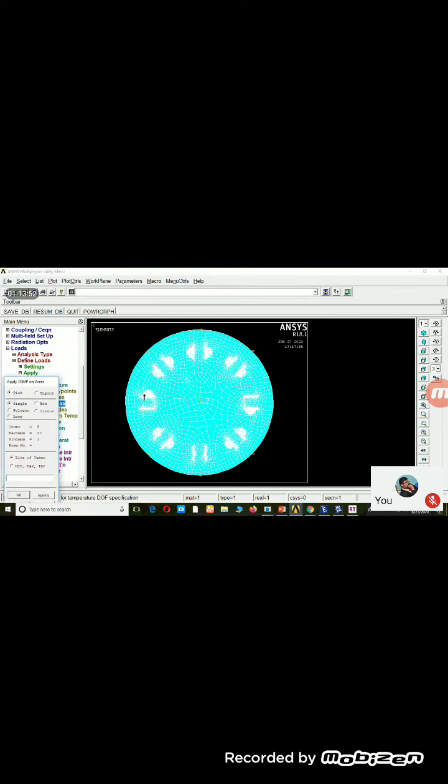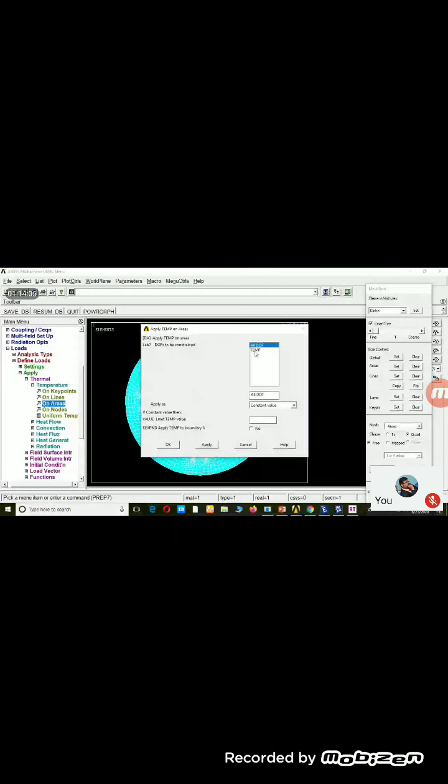Select the area temperature, that is the temperature found in the coil. Either we can go for the temperature as the heat source, or we can go for heat generation as the heat source. I give the temperature as 35, which is a default one. Suppose we are giving the heat generation as the input in the coil, the formula for calculating the heat generation is losses divided by the surface area of the coil. Losses means you have to include both ohmic losses as well as iron losses.